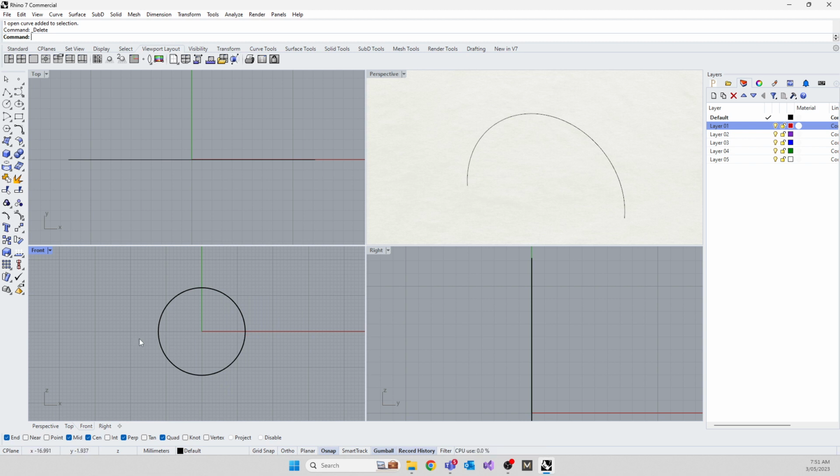All right. So the quad snap is I want to draw a curve. So this time I'm going to find a line from here. So there's the line. There's a little icon. I don't want this line. I don't want a polyline. I want a single line. So I'm going to tap the little arrow and select the first one, which is single line. All right. So I want to find the exact left-hand side of the circle.